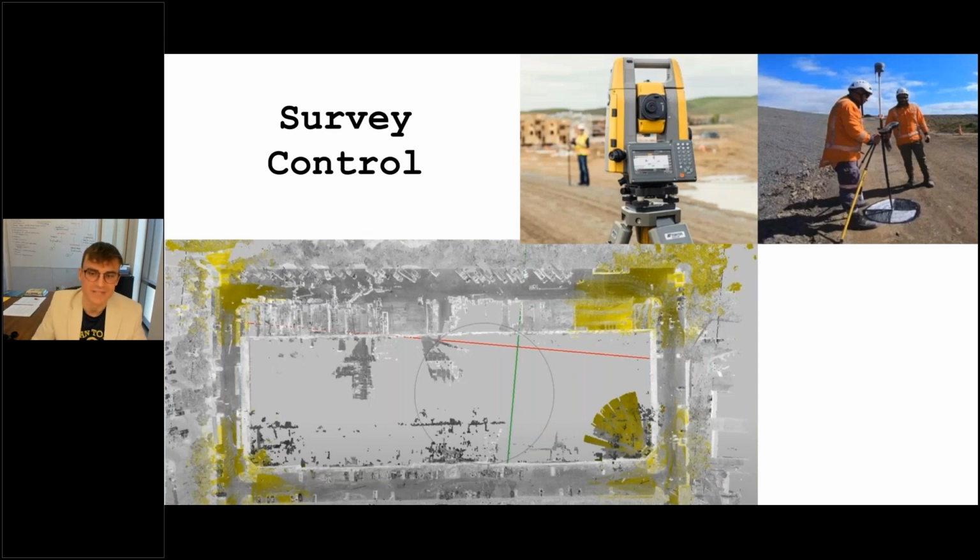If that wasn't complicated enough, I'll throw one more thing at you, and that's survey control. You may need to have a licensed surveyor come out and measure some of your targets with a total station to get those points really, really accurate. Hiring surveyors is not expensive. If you need survey, do not hesitate to get control done.